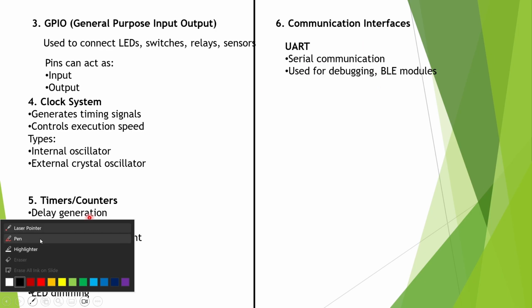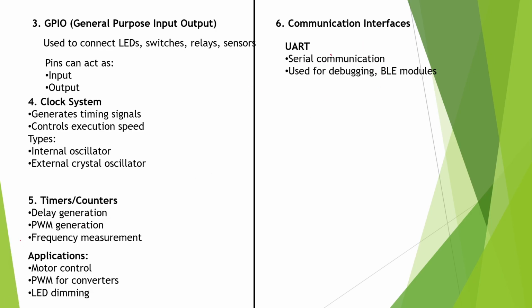What are the pins of UART? TX and RX. We will see every communication protocol in detail. How will the RX and TX be connected with each other in UART? That connection is important basically. RX will be connected to the TX of the other microcontroller, and TX of one microcontroller will be connected to the RX of another microcontroller. So this is very important.